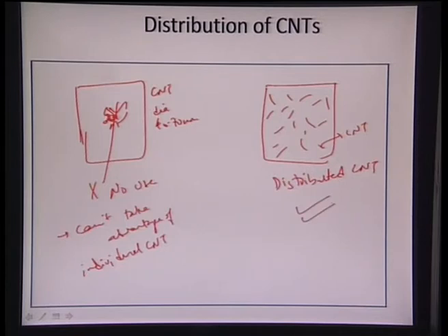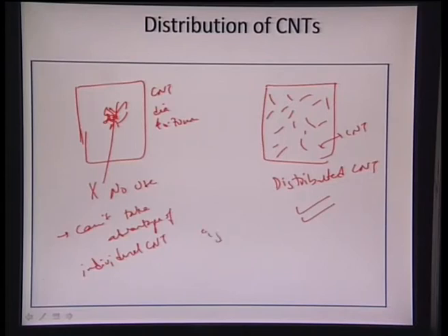So that is what we are really looking for. Owing to the very high surface area of carbon nanotubes, they tend to agglomerate. That agglomeration has to be avoided in the first stage itself, that is the blending of powder. If you are utilizing a powder which serves as a feedstock for plasma spraying, we take powders of hydroxyapatite and mix them with CNTs. CNTs should get dispersed in the powder formation itself, so in the powder feedstock we should have dispersed CNTs in the matrix.